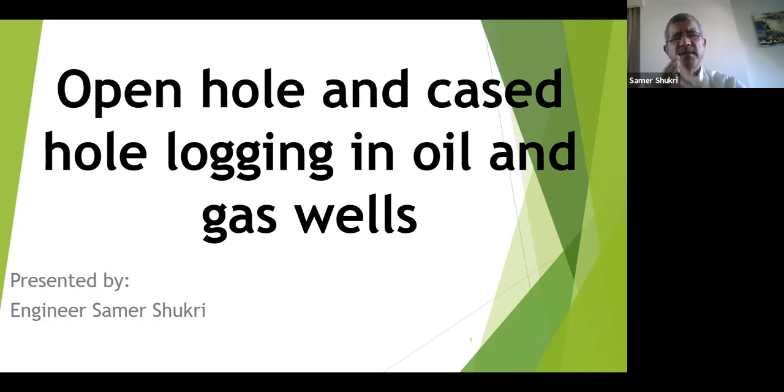In this case, we can see what is the plan for production or injection for the future for this well. And during the production of the well also, we can see when to do this log. For example, if water cut increased from 0 to 50% or 20%, you have to investigate where it is coming from.